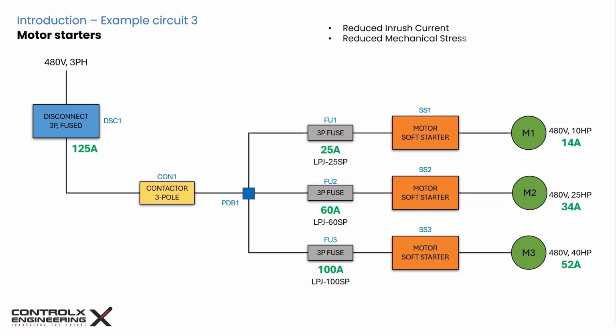loads. Full voltage starting can cause high torque, leading to belt slippage, shaft stress, and wear and tear on the gearboxes. Soft starters allow smooth acceleration, thereby reducing or eliminating mechanical damage. Motors and mechanical components last longer with soft starting, and reduced thermal stresses on the windings means fewer insulation breakdowns. Soft starters reduce peak demand charges from utilities. By limiting the starting current, soft starters help avoid tripping breakers or blowing fuses during startup.